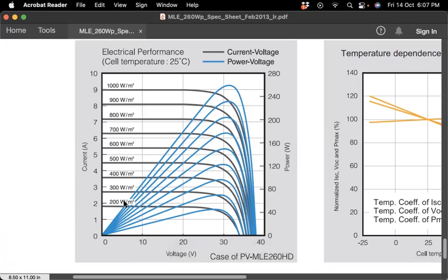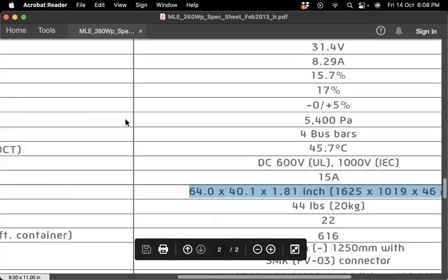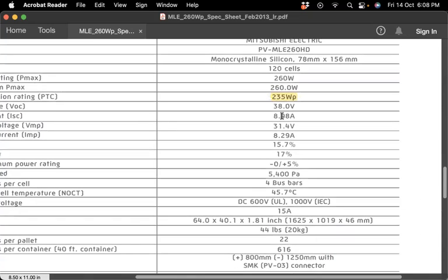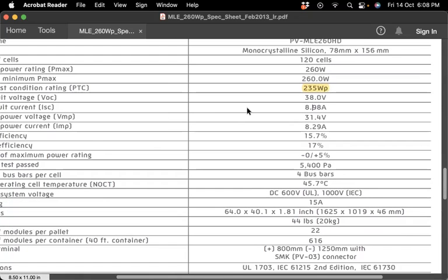And from this perspective, my dear students, you can use solar cells as a very accurate sensor to sense irradiance. So, for example, if you make a short circuit test for your solar cell and you find that your current is around 8.9 ampere, which is the short circuit current, then you can assume that at this time of the day, the irradiance is around 1000 watt per meter square.